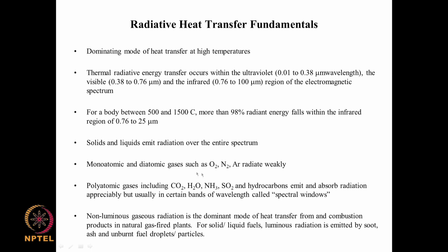Monoatomic and diatomic gases such as O2, N2 and argon radiate weakly, they do not participate significantly. Polyatomic gases including carbon dioxide, steam, ammonia, sulfur dioxide and hydrocarbons emit and absorb radiation appreciably but usually in certain bands of wavelength called spectral windows. So, why are these gases important?